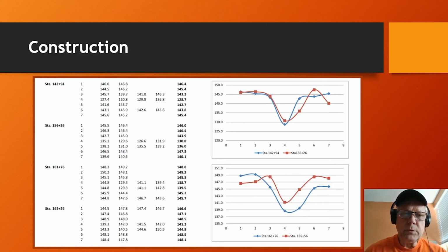There's a construction project where a testing firm did density testing heading into coarse areas and out of coarse areas, and you can see the dip they found was 15 pounds per cubic foot. That's significant, and I believe the roadway's recommended fix was to do pavement patching at all the areas of heavy segregation. If not that, then maybe they did some type of seal coat or double chip seal and things like that with the contractor. Anyways, this is just a data collection process that is visually easy to see on the right-hand side of how bad the segregation was.